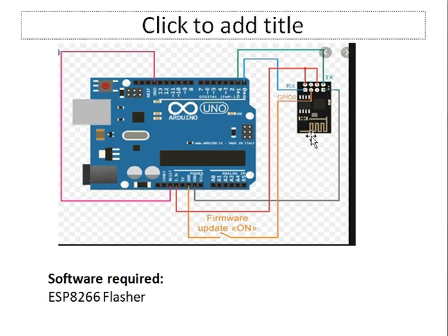Now here, if you want to place data onto the cloud, then you can use this module. You can have data stored in the Arduino, which means you can connect some input devices and grab the sensor values. After that, you can transfer those sensor values using the Wi-Fi module onto the cloud. So for that, this is essential. If that application needs to be implemented, then definitely you require a firmware to be dumped onto this IC.